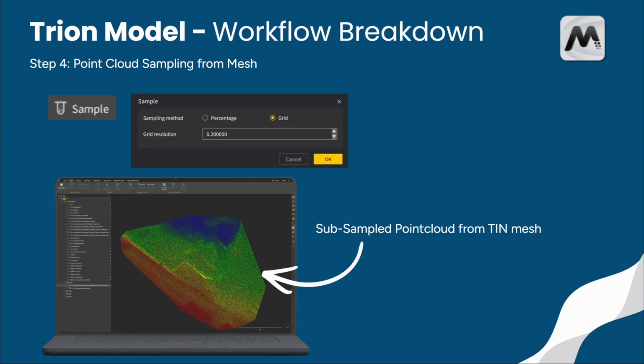Here we can define a suitable grid resolution to keep the dataset efficient and well balanced in terms of detail and file size. The advantage of this triangulation and resampling workflow is that previously empty areas now receive new points based on the generalized terrain surface. In other words, the holes are no longer empty. They become part of a continuous terrain dataset.